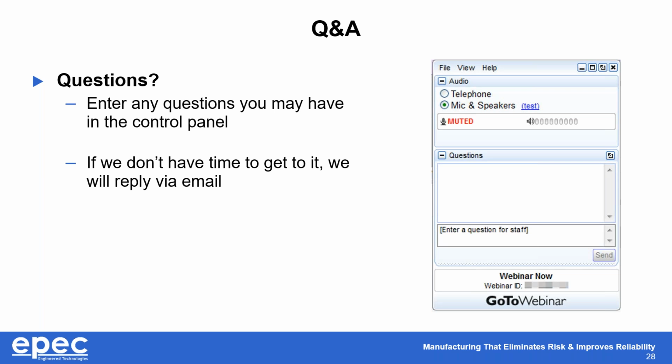we solely use dome switches made of stainless steel. We do not use polydomes. We do not use domes made of other non-metallic materials. And the reason is because dome switches are not expensive, but they're a critical part of the assembly. And we believe using a high fidelity dome switch is well worth the small costs that you need to pay above and beyond some of the less expensive carbonate type technologies or polydome technologies.